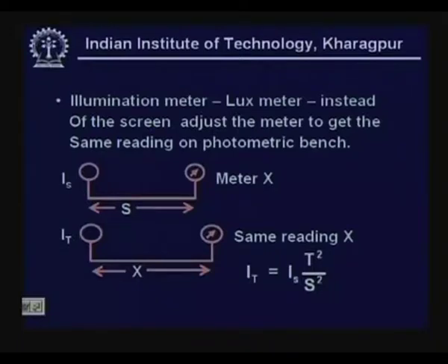Then the next stage, we take the test lamp, we replace the standard lamp by the test lamp, and then move or vary the position of the lux meter to obtain the same reading of illuminance.